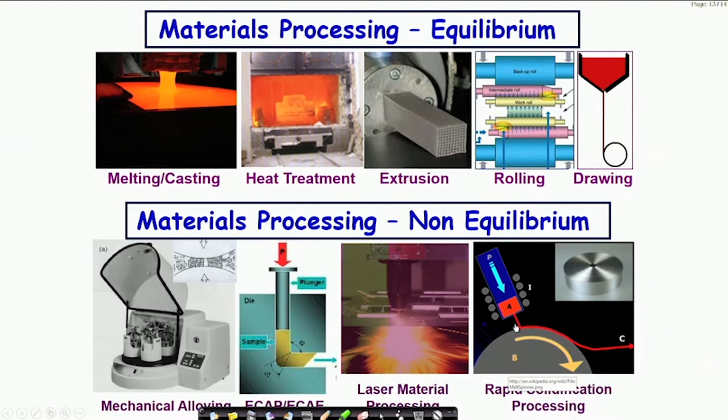We can solidify a liquid onto a rotating wheel, rotating at a certain RPM, but most importantly the wheel is made up of high conducting materials like copper, which allows very fast cooling.